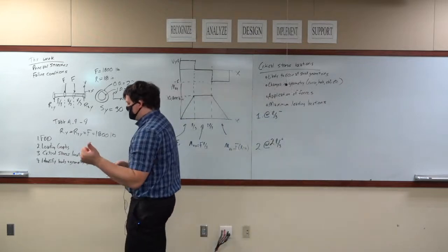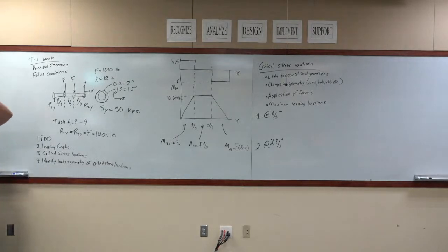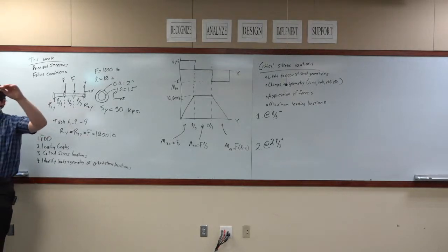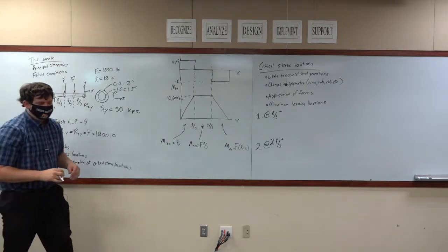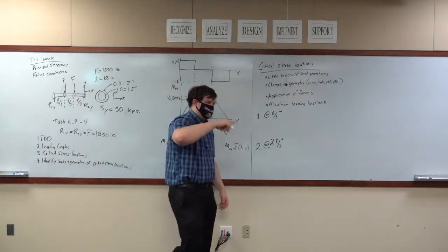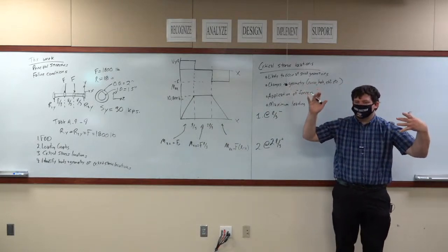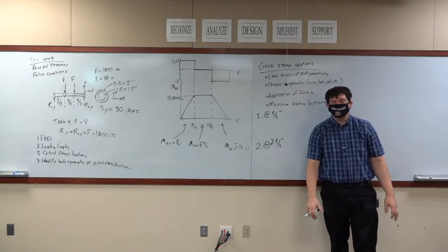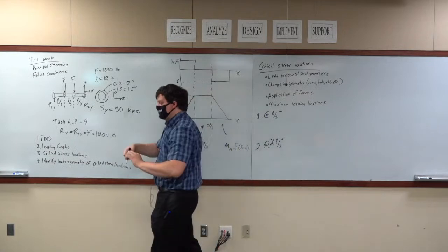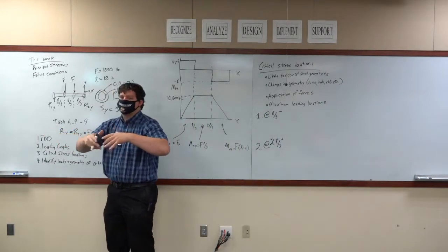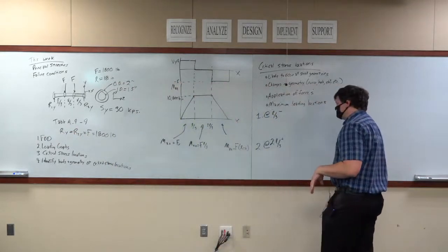Bending stresses create normal stresses, your sigmas. Because again, at the top of the beam, where there's tension, it'll be stretched out. At the bottom of the beam, where it's in compression, it'll be smashed. And then lastly, torsion creates shear because it doesn't cause it to get bigger. You twist it and it doesn't grow, at least for most materials. Some materials, that's not true, but not the materials we're looking at. It just deforms. So that's what we're dealing with. Just keep that in mind for later.